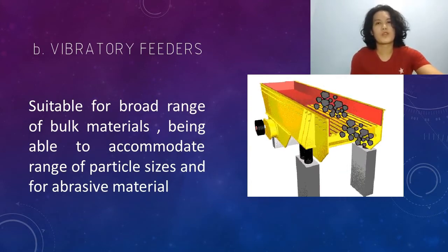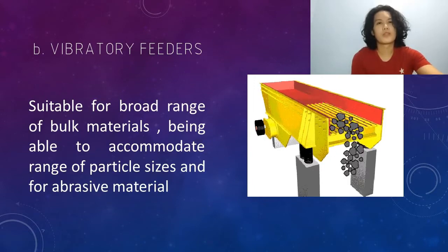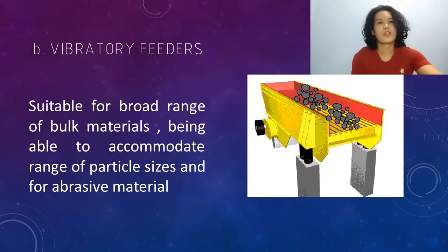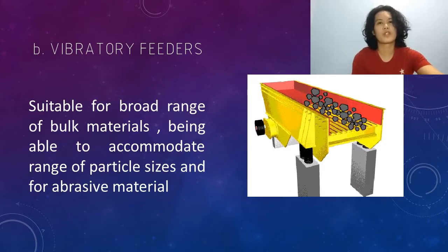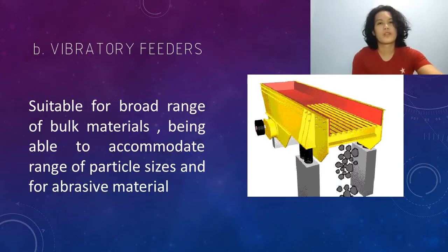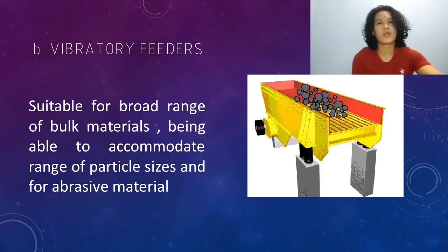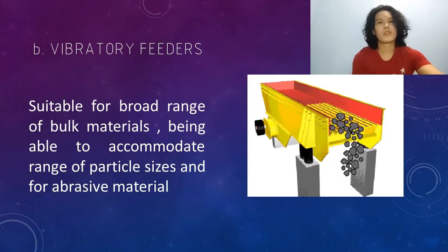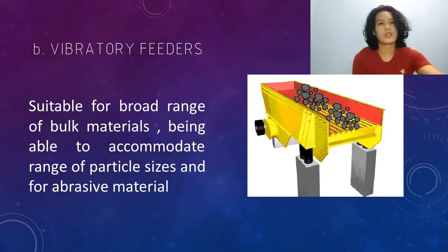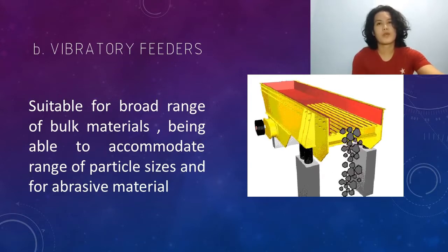As for screw feeders, they can deliver dense slurries and dry granular products with great accuracy at a range of operational speeds. Screw feeders are designed to volumetrically measure material from a hopper, container, or silo at a controlled rate. Many screw feeders use adjustable speed drives to allow the material flow rate to be varied.